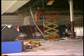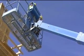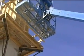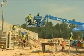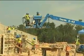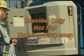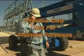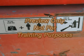Personnel should always stand firmly on the floor of the lift. Never sit or climb on the basket or guardrails, or use planks, ladders, or other items to attain a higher work position. If additional height is needed, then the lift should be extended, or if necessary, a different lift used that is appropriate for the job. The lift operator should know the total load of the lift, including tools, supplies, and other employees. The weight of the load should be within the manufacturer's suggested maximum safe working load.